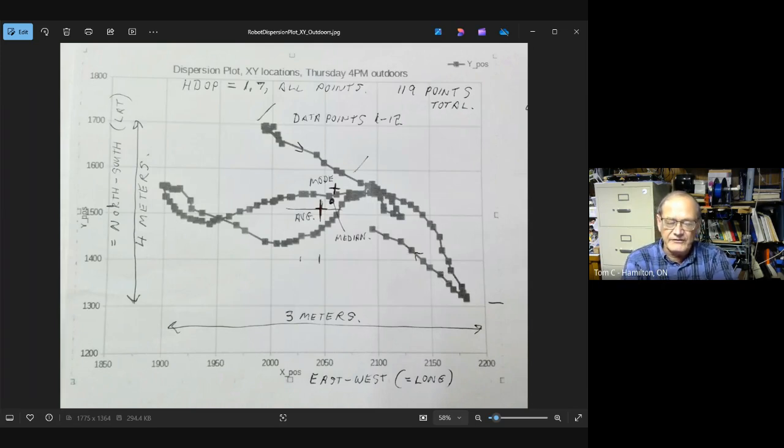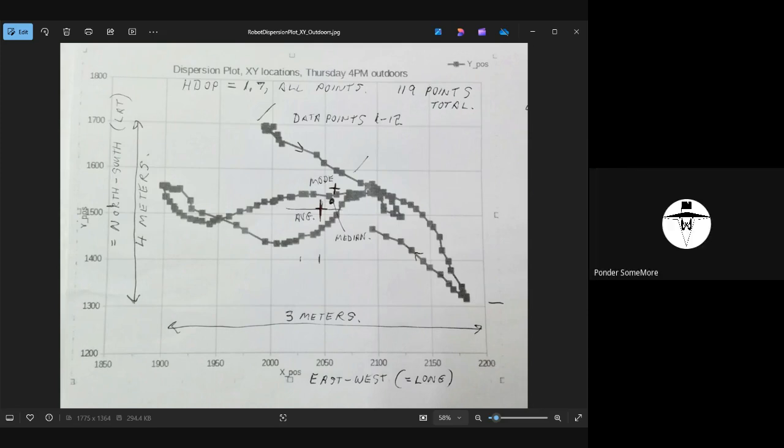I would previously have said that I've probably got about the best conditions I can get for operations. I've got 6 satellites, I've got a 1.7 DOP, and I'm collecting data. And then I plotted this stuff. So first of all, examining the dispersion, the first data in the set is up here. And then as you look at the progression over time...